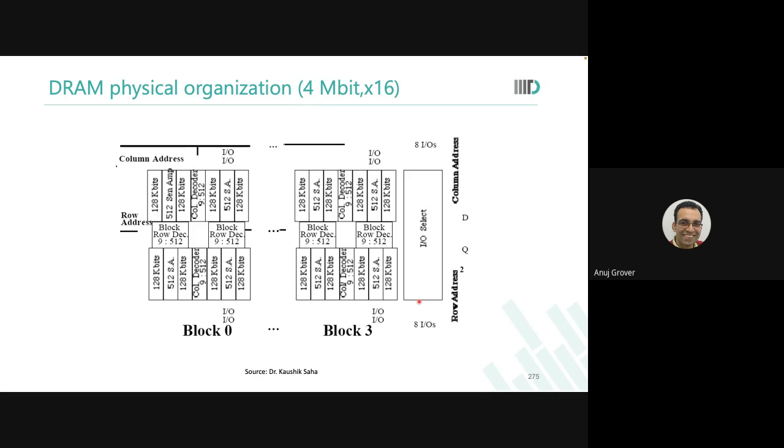In any given word, only 1 bit will get corrupted. See, DRAM cells are much smaller. So if a high energy particle comes, it can corrupt not just 3 or 4 bits, it can corrupt 20 bits in one go. If those 20 bits were part of the same word, there is no way to correct it.